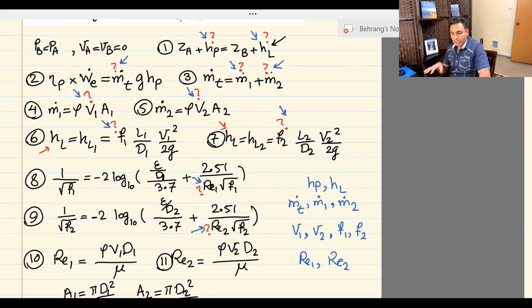However, there is some trick to it. Friction factor is an interesting equation, the Colebrook equation. You can probably use the other equation, the Haaland equation that we have in the book. But the Colebrook equation is the Moody chart, basically. First of all, you might ask how do you know this is going to be turbulent? I would say this is turbulent. You're dealing with an 8 kilowatt pump, and these diameters and water, from experience, it's turbulent. Also, it says commercial steel. If it is commercial steel, I know this is going to be turbulent. So I directly went for the Colebrook equation. I didn't need to write 64 over Reynolds number or anything like that. This is not a smooth pipe, and this is definitely not going to be laminar.